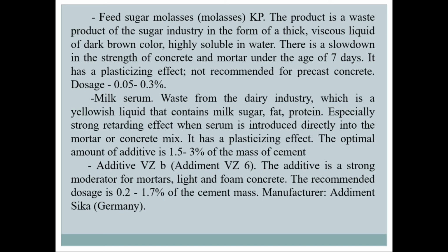0.05–0.3%. Milk serum, a waste from the dairy industry, which is a yellowish aqueous liquid that contains milk sugar, fat, protein, has an especially strong retarding effect. When serum is introduced directly into the mortar or concrete mix, it has a plasticizing effect.